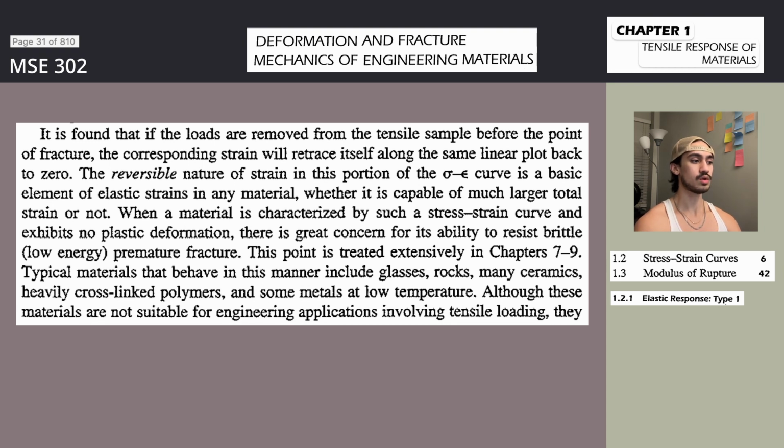For the case of hexagonal crystals, the matrix in equation 1-11 reduces to equation 1-17, where L sub 1, L sub 2, L sub 3 are direction cosines for directions in the hexagonal unit cell. From equation 1-17, note that in hexagonal crystals E depends only on the direction cosine L sub 3, which lies normal to the basal plane. Consequently, the modulus of elasticity in hexagonal crystals is isotropic everywhere in the basal plane.